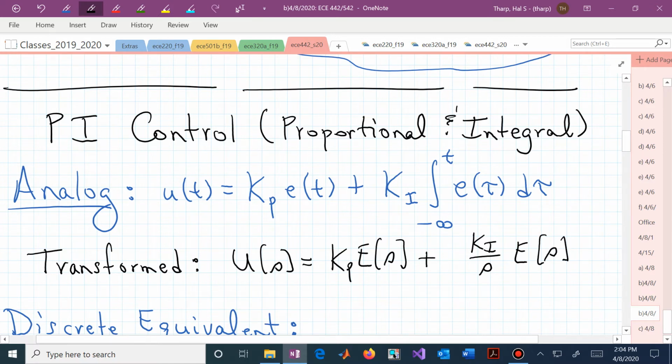That's now what the PI controller looks like relative to the error, and that error signal is usually a comparison of the reference input with the output. That's how we build or generate this error signal. We scale it, and that's the proportional term in our PI controller. We integrate that error and scale that with k sub I, and that's the integral term.